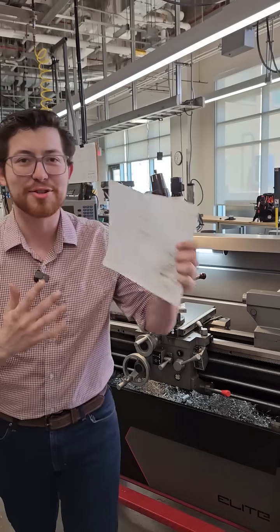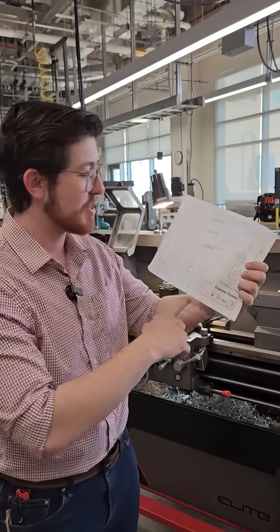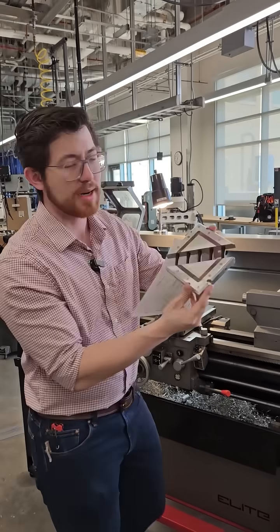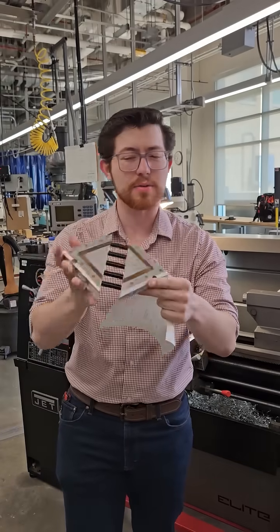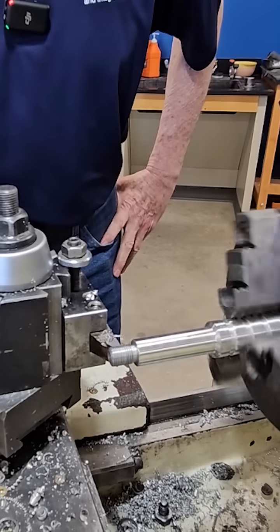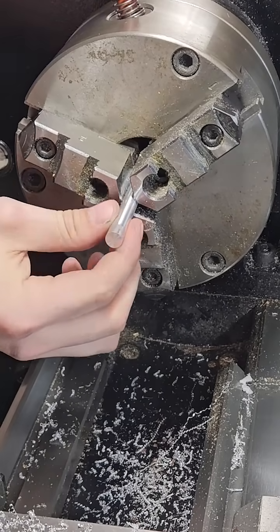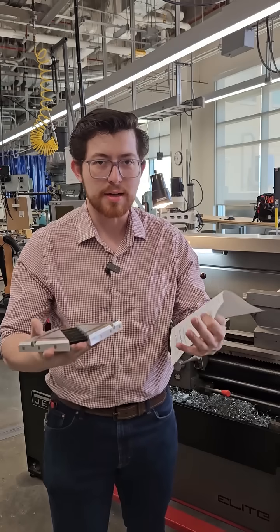Tolerances. Yes, tolerances are super important when it comes to machining things, because that little tolerance is going to dictate whether or not I can properly do whatever weird thing I'm making with press fit holes, clearance fit holes, whatever it may be. Those tolerances are the only thing that's going to allow that to happen, or we're going to get parts that don't line up, don't fit, or match.